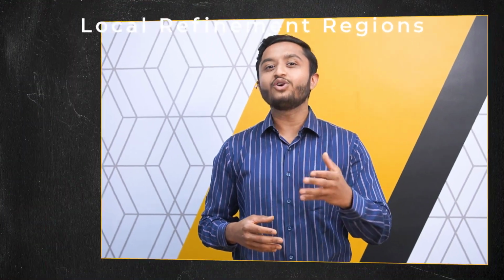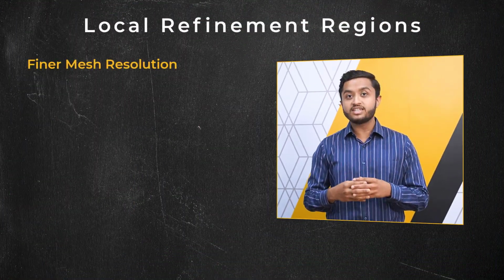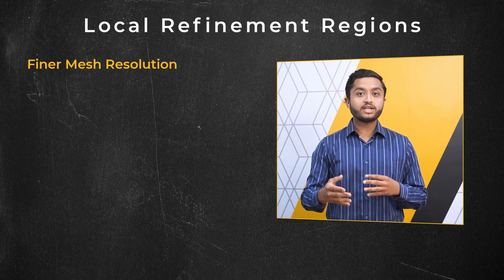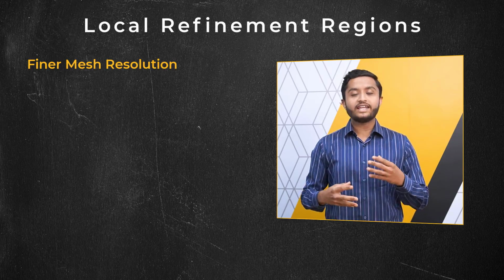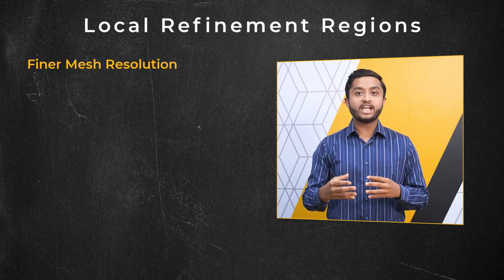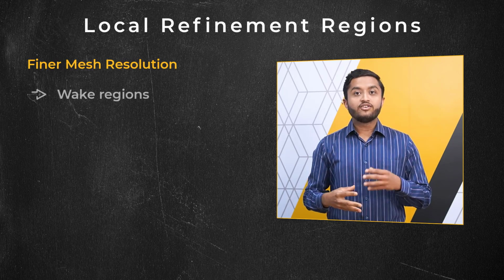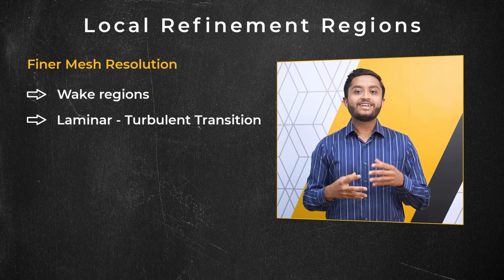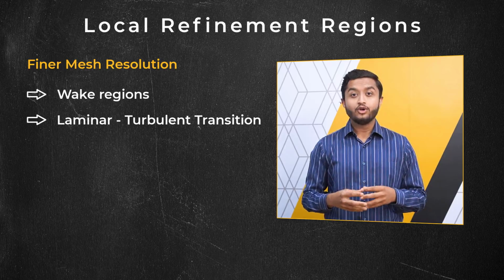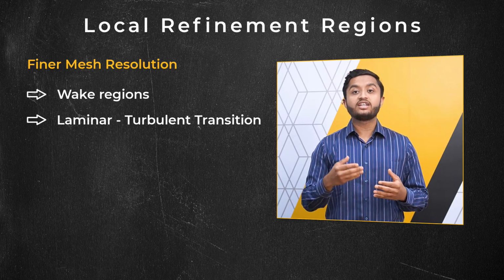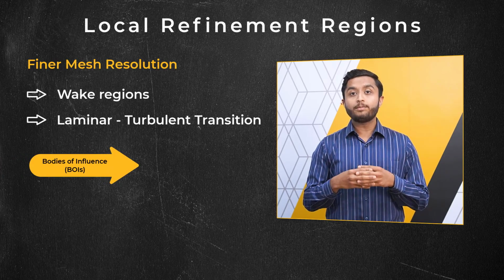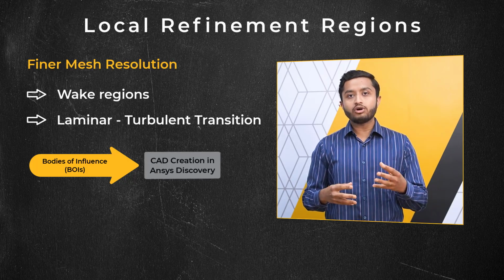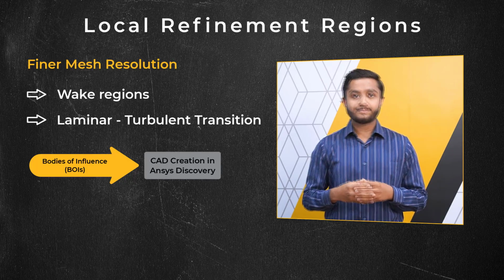For most fluid flow problems, a finer mesh resolution may be required in specific regions of the computational domain to resolve and capture certain fluid dynamics phenomena like the wake regions of the bodies, laminar-turbulent transitions, etc. For creating such localized refinement zones, the usual practice is to define bodies of influence or BOIs during CAD creation.